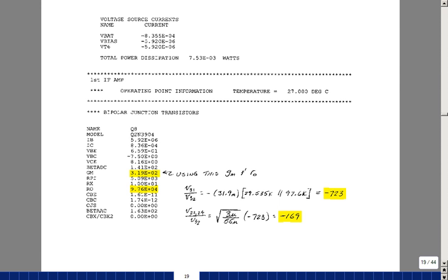So in recap then, we've got two bandpass filters, both with fairly high values of Q. You see the sharpness in the filter, and also quite a bit of gain. So we're going to be passing the received signal after it's been mixed down through two bandpass filters, just letting the 455 kilohertz signal through, and hopefully rejecting the nearest radio station that's been mixed in with it.